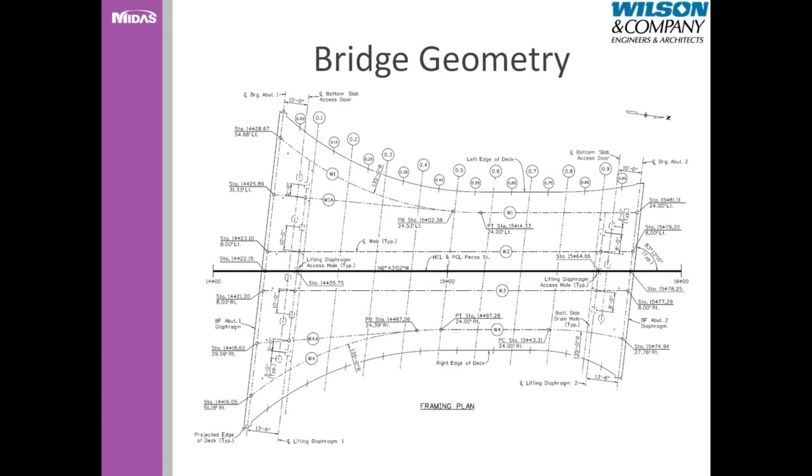All right. So here is a plan view of this structure. It's a local bridge over Interstate 70 down here in Denver, Colorado. As you see, it's not symmetric in any real way. You have the flared webs out here that bifurcate. So out here on the wide end, we have 6 webs. Get here towards the middle, we're reducing that down to 4. These webs vary along the same radius, but they terminate at different locations.